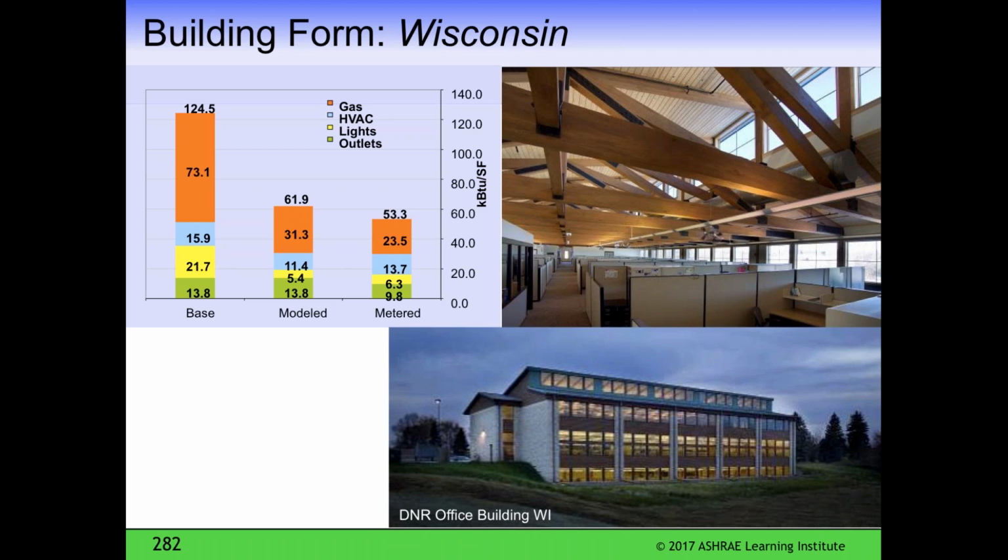And you see at the upper right of this slide that you have a very pleasant interior space that doesn't have glare issues. It's actually not using a white ceiling, but it's using a wood ceiling that reflects light down, but it's very soft. It has high partitions for privacy, and yet because the partitions are not facing in toward the windows, you have virtually 100% of daylighting in this space. It's really a nice solution.